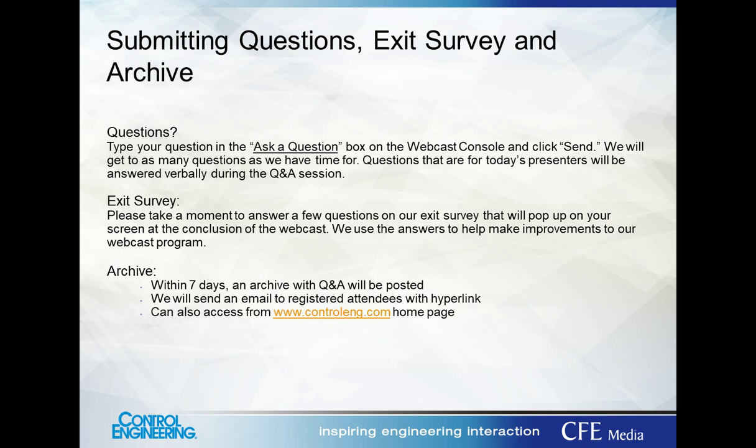But the bad news is this type of performance does not really lend itself to direct measurement or mathematical measurement, but can really only be gleaned by overall metrics such as loops in manual, right? If you have loops in manual, then maybe something's wrong with your tuning, or multivariable loops in manual, or the number of alarms. So we can only glean optimal tuning or whatever modeling based on our overall reliability and availability. Okay.